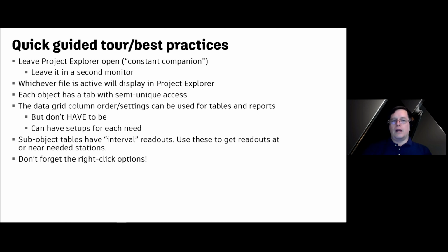Also, don't forget the right-click options. The right-click is important to the base AutoCAD and Civil 3D tools that we use, but it's also important inside Project Explorer. And there are some tools that I think the easiest and best way to get to is the right-click menu. So keep that in the back of your mind as you're working through, especially as you're learning Project Explorer, that the right-click menu is something you're going to want to employ as you go here.